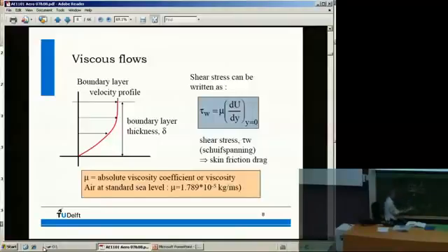So du dy, you should put it the other way around, if you normally use plots like this. Then you should turn it around, and this one is steeper than this one. So the u is increasing faster if you go up. So the thin boundary layer close to the object has a higher friction force.